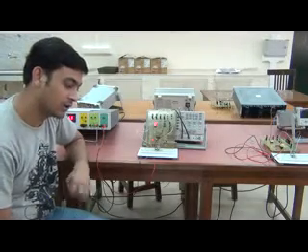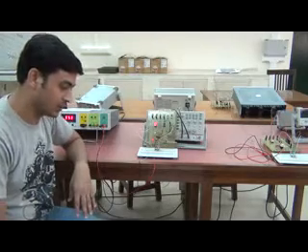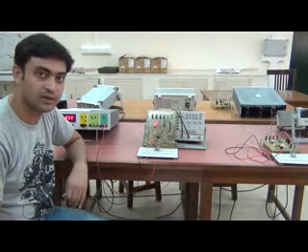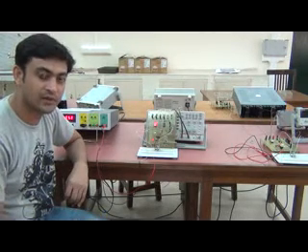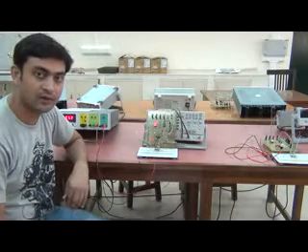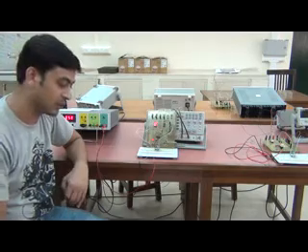The truth table, or the sample table, for this synchronous divide by 3 counter is given in the handout. In this, the 11 state is unused and the rest of the 3 states are implemented.